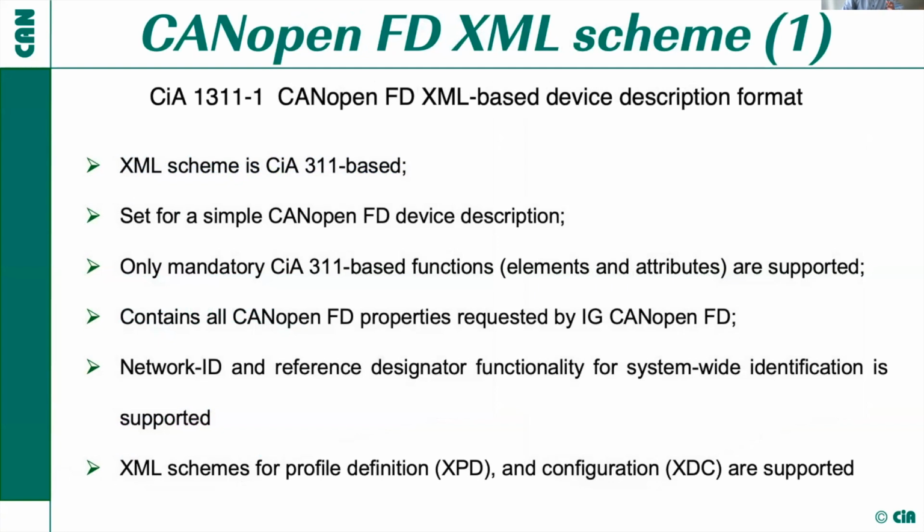Just a few slides about the XML schema, because the standardized approach suggests all the XML-based device descriptions will be generated, as is usually done, based on an XML schema. For that XML schema, we took an existing one and reduced it to the minimal necessary functions. All mandatory functions are in there. This XML schema is the base for generating every XML-based device description, device configuration, and profile description file. One schema allows generating all of those.